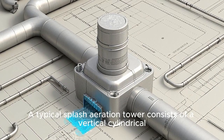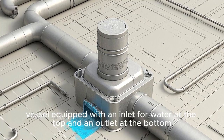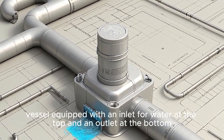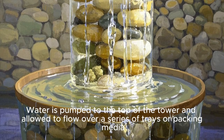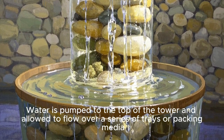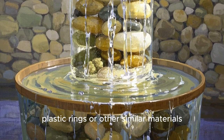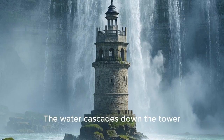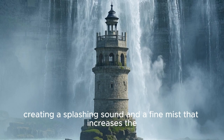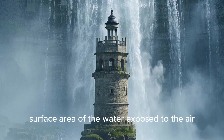A typical splash aeration tower consists of a vertical cylindrical vessel equipped with an inlet for water at the top and an outlet at the bottom. Water is pumped to the top of the tower and allowed to flow over a series of trays or packing media, which can include bioballs, plastic rings, or other similar materials. The water cascades down the tower, creating a splashing sound and a fine mist that increases the surface area of the water exposed to the air.